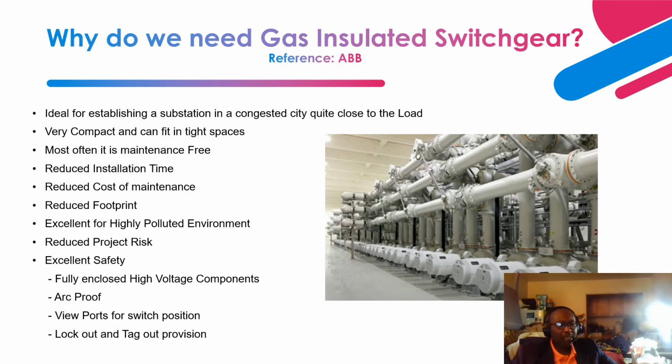Next, a gas insulated switchgear is very ideal for an environment that has a high amount of pollution, right? If you look at a lot of these industrial facilities, they have high oil contaminants, sand contaminants, dust contaminants, and also if you have a facility that is close to the shore, you have salt elements that are intruding into the switchgear.